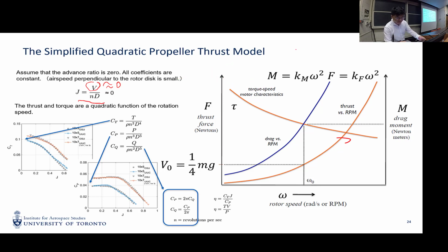So if this is a rotor disk, and if this one is the forward velocity, then in terms of performance calculation, you still need to get the perpendicular component so that you will have an accurate estimation of the J. But in terms of control, we do another simplification. We just assume that this J is 0, and any other uncertainty caused by this approximation is handled by the controller. So we just treat the unmodeled dynamics as part of the disturbance.